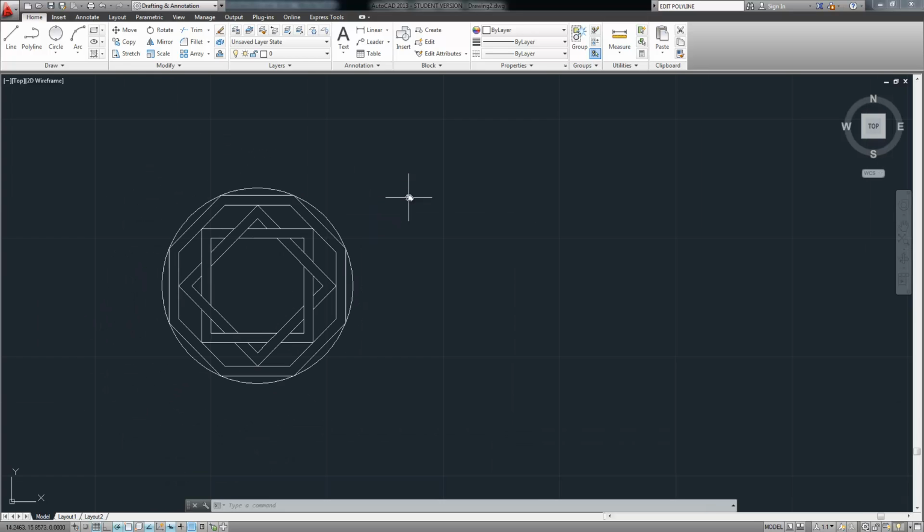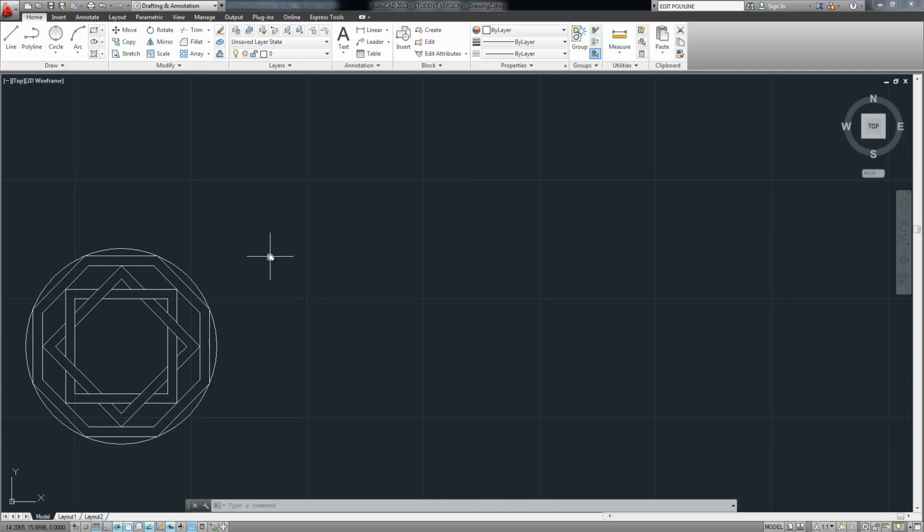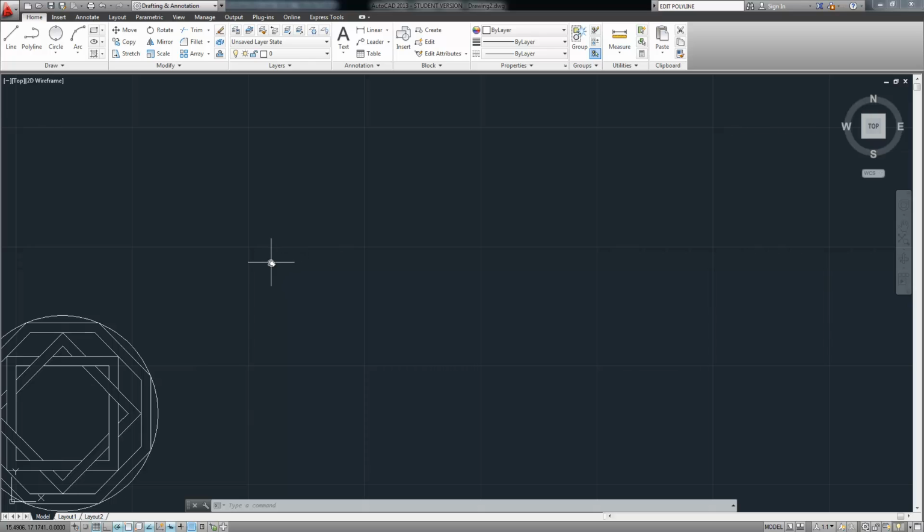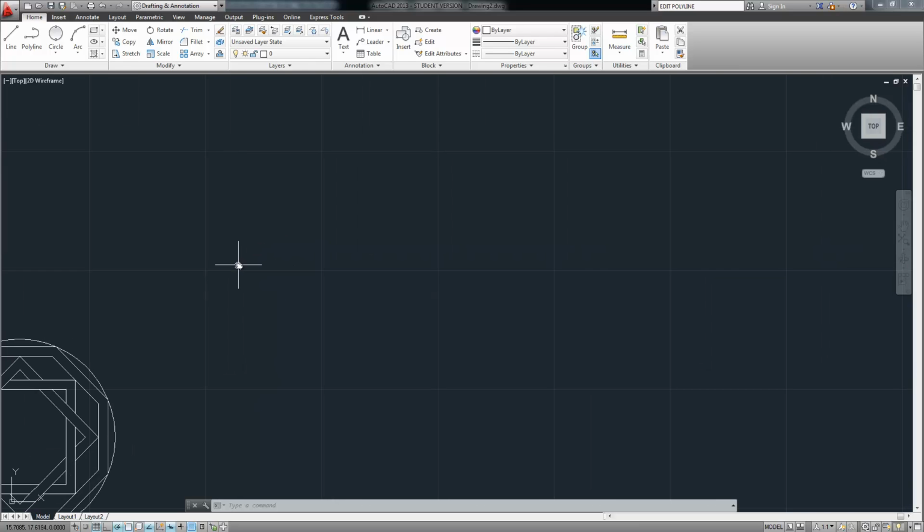Okay. Alright, so moving on to number 2. I'm sorry, that was number 2. Moving on to number 3. Go with what you know. And we're given the radius of 1, 2, 3, 4, 5, 6 different circles, plus 7, 8 larger circles that are using the tangent radius. And then for all of the rounds, we'll be using the fillet command. So it's not too difficult here, just go with what you know and draw all these circles that you know.